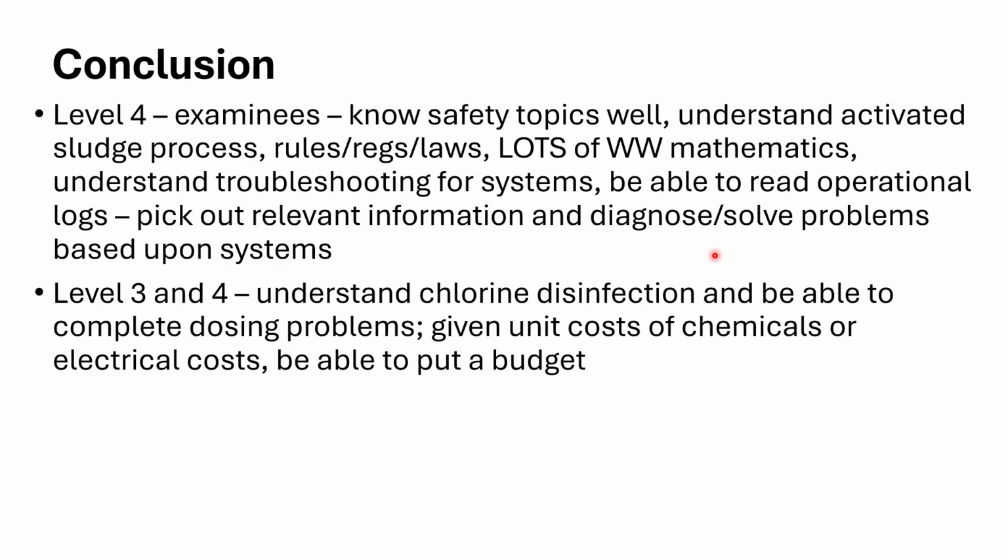For level 3 and level 4, you've got to understand chlorine disinfection and complete dosing problems. If you're given unit costs of chemicals or electrical costs for pumps, then you've got to be able to put together a budget. What's it going to cost to run a pump for a month with these system characteristics, with this flow rate, with this head, with this friction loss?